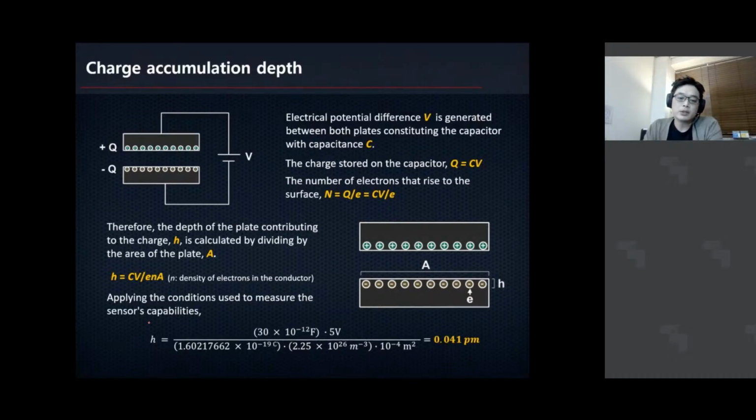What's important is that there is no conductivity of the material in that governing equation. So the conductivity of a conducting material does not matter when you build the capacitor. As long as you can accumulate charge at the surface of a metallic surface, it's still usable as an electrode for a capacitor.